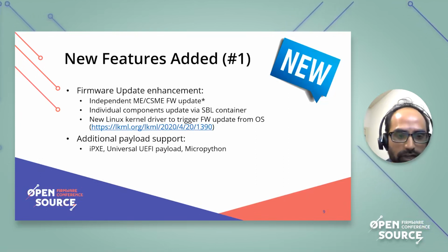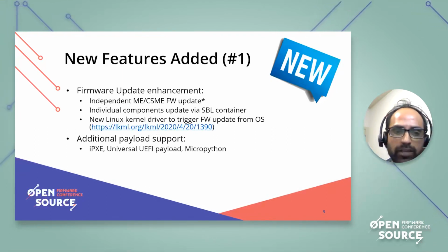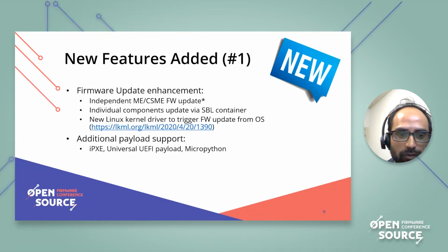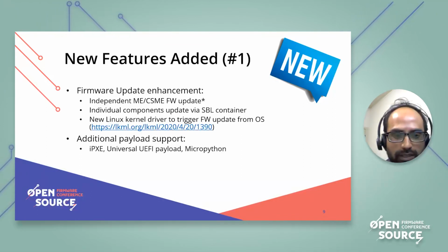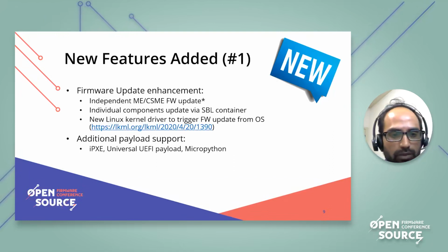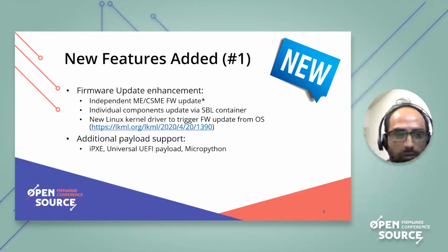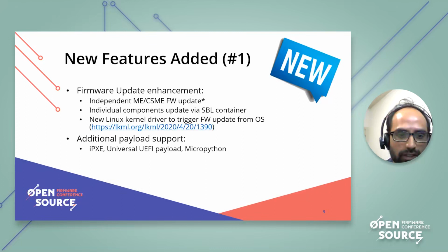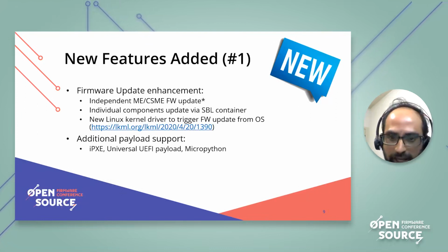And there's a specification called the Universal UEFI Payload Spec, which provides a universal API so that any bootloader can boot any payload that supports this API. For example, Coreboot can boot a Linux payload following this API, and Slim Bootloader can boot other UEFI payloads or Linux boot or U-Boot, etc. Slim Bootloader also has support for this universal UEFI payload-based API.